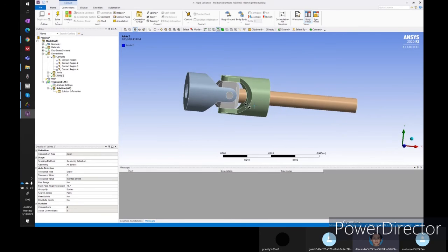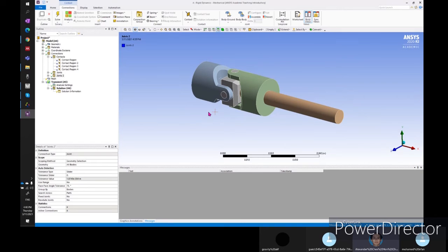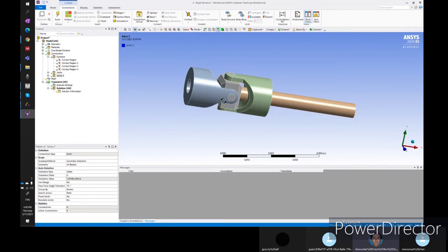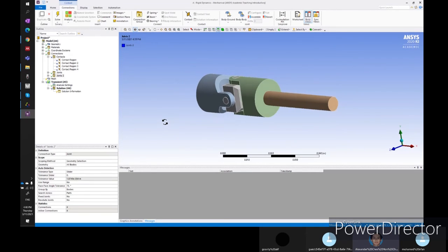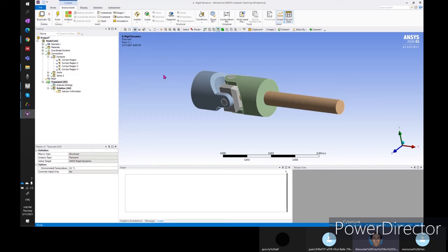So over here, let's say I would like to set a fixed point over here. Later we can try others. So that means I'm just assuming that this face is attached to another machine, so they are fixed. Okay, during static structural, we also know that we need to fix the position, right? But here, if you look at the Transient here, you may not see a fixed support, and it is not allowed. So we cannot use the static structural mentality over here in the dynamic. So over here, we also use joint.